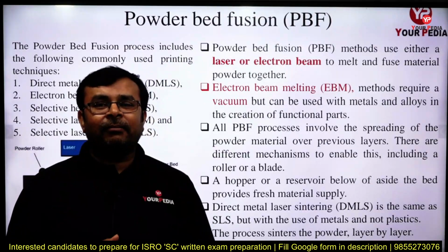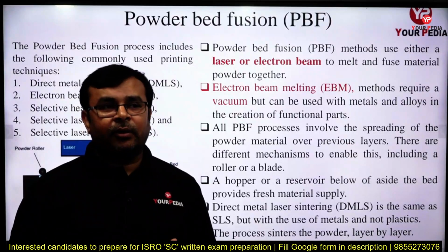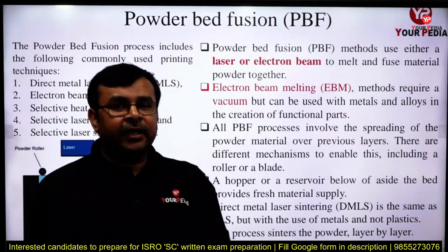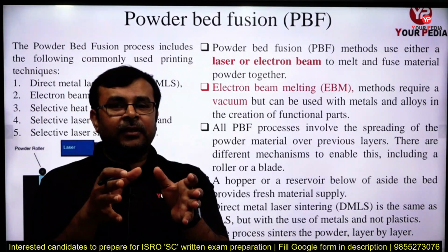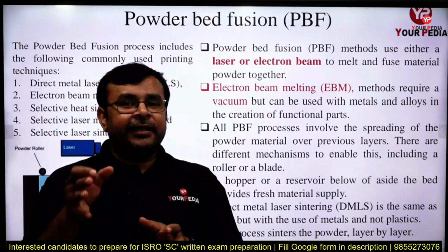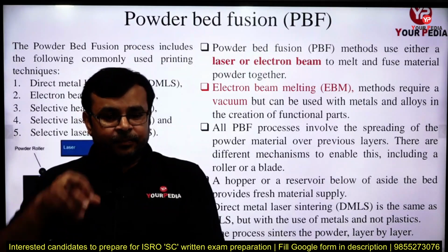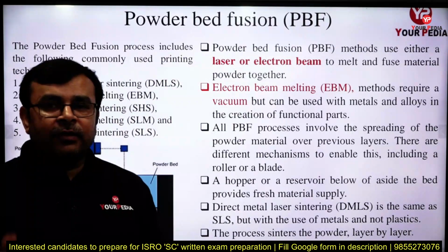Now if we use this technology in the same manner, instead of creating a joint, we just concentrate the heat at a certain region, and we provide the system in such a manner that it can move in the xy direction. Is it clear? We control this electron gun with the help of a computer-aided machine.